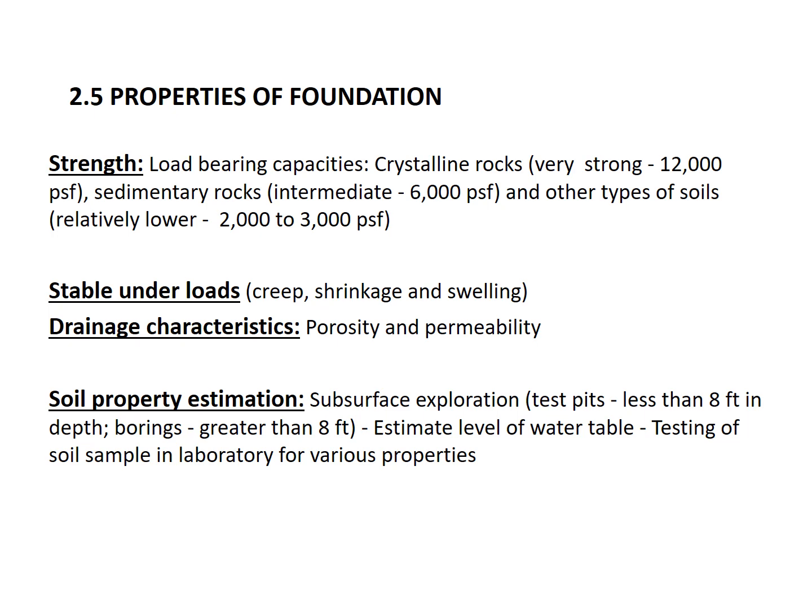Now, soils are fine to build on. It's just that anything above 3,000 psf is already exemplary because it's so solid, and that's why solid rocks can carry high volumes of weight with no problem whatsoever. But the 2,000 to 3,000 range is fine too. So the thing is that foundations need to be stable under loads, that they don't have any creep or shrinkage and swelling. There's also an item about drainage characteristics.